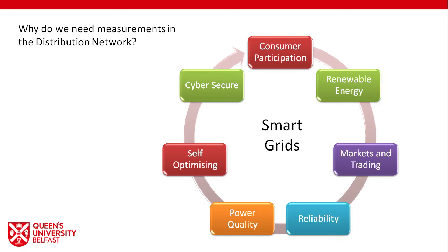It features renewable energy, for example, solar panels on people's roofs. It can include wind turbine generators. It has very high power loads, such as electric vehicles. And indeed, there is now an ever-increasing push towards electrification of things like home heating. This means that the distribution network now has to transport more power than it previously did, and it might also have to deal with reverse power flows. That is, power is actually being pushed from the distribution network back up into the transmission network.